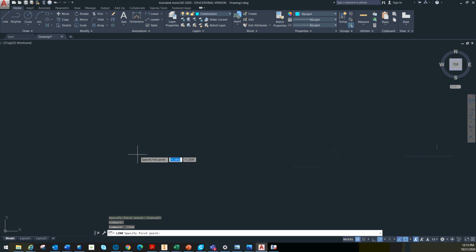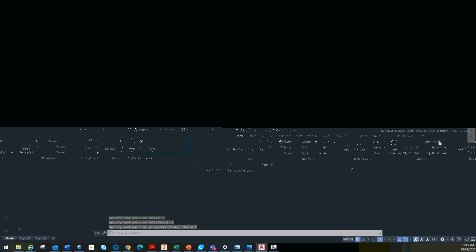Okay, a couple other tools. We're going to look at drawing a circle. Anytime that you draw a circle, you need to know where the center point of that circle is. So oftentimes when you're drawing a circle, it's handy to use, say, a construction layer line, mark out a distance, let's say 5 units over and 2 units up from that point. So once I have that information, I can then click to my 0 layer, click on circle.